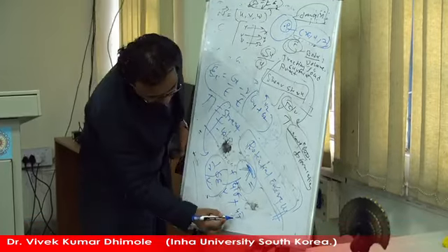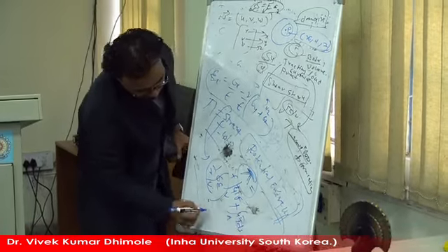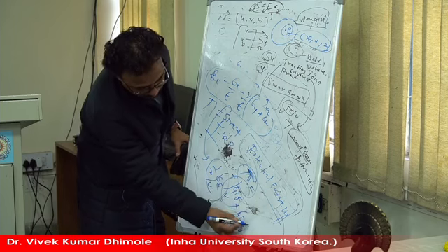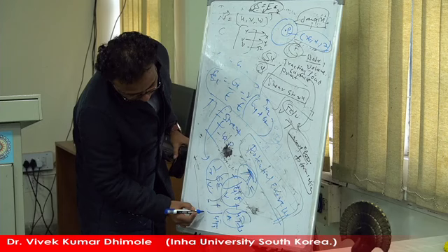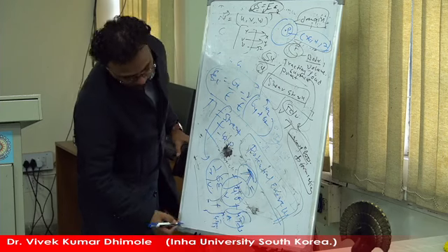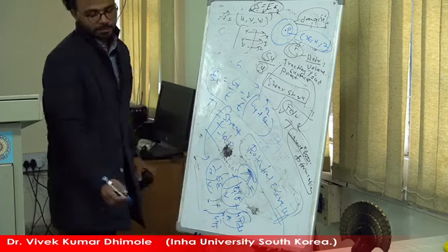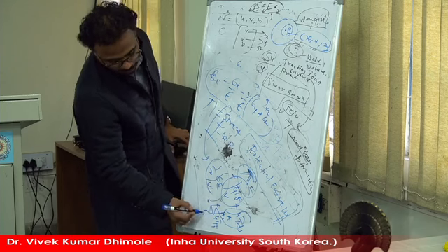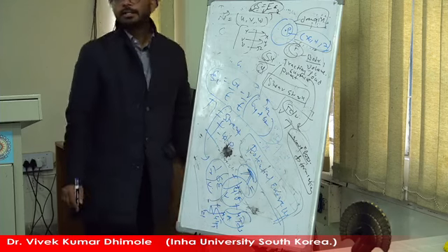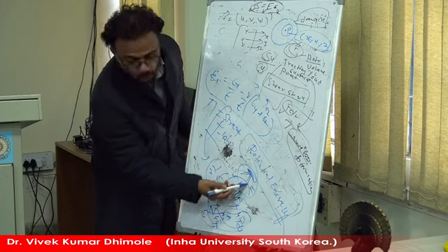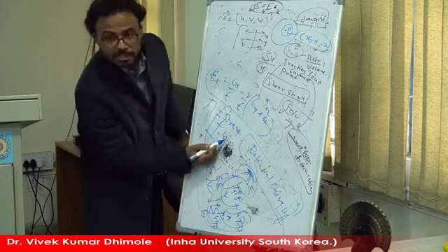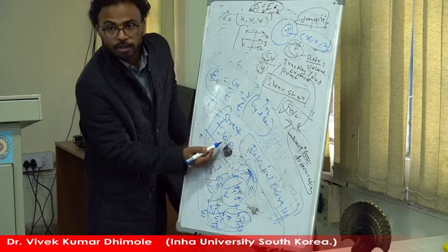u transpose times traction over dS, area A. So this is the volume, and this is the area. Point load plus u transpose P_i, summation from i equal to 1 to n, points 1 to n. So this is the way we are summing all the forces in the work potential.